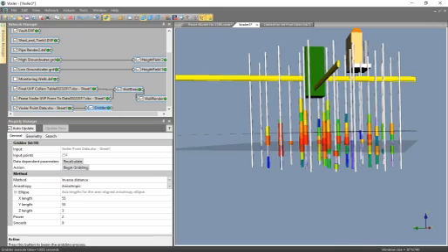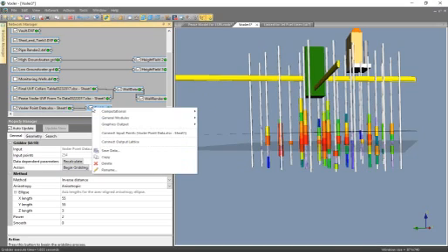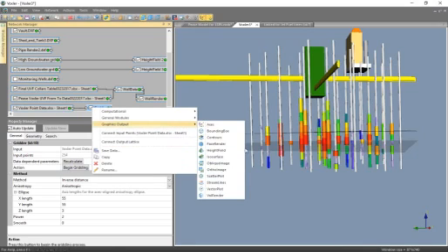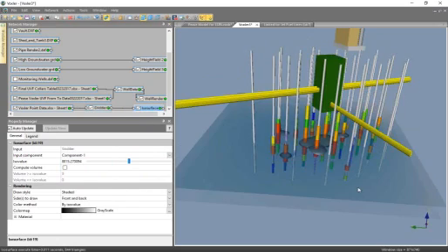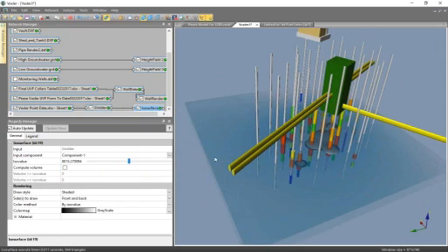And so now that the data is gridded, we can delineate the concentration in the soil of the jet fuel or the LNAPL by adding an isosurface to the gridder. Okay, and so we can simply right-click on top of the gridder and use graphics output isosurface, right? And you can see it down there a little bit. I'm going to go ahead and change this color mapping to rainbow.